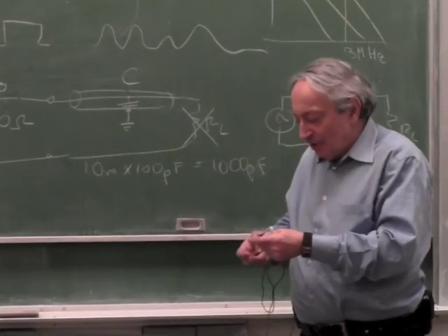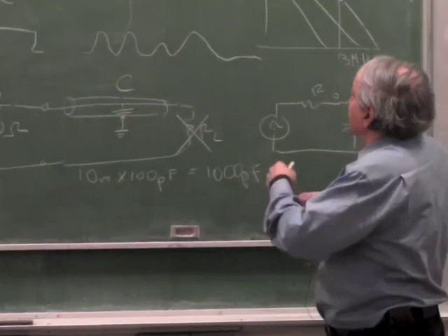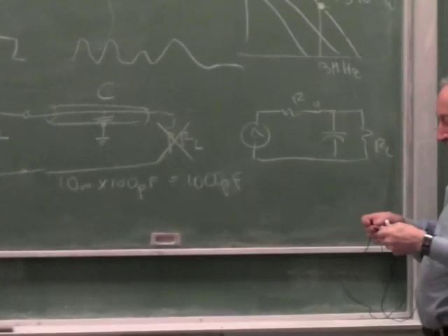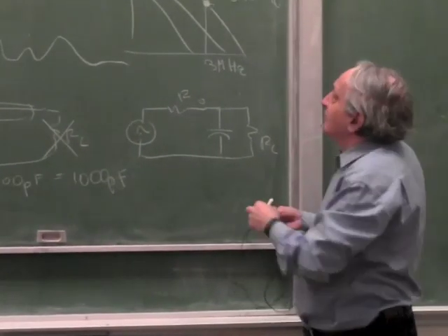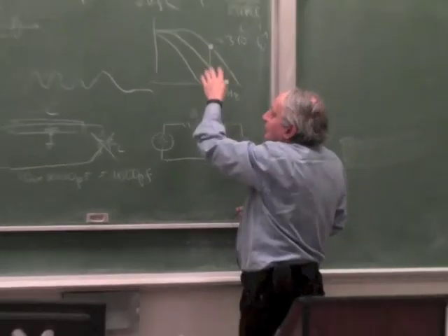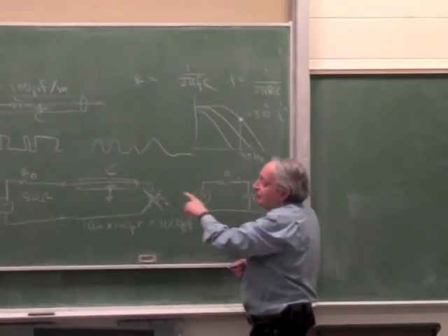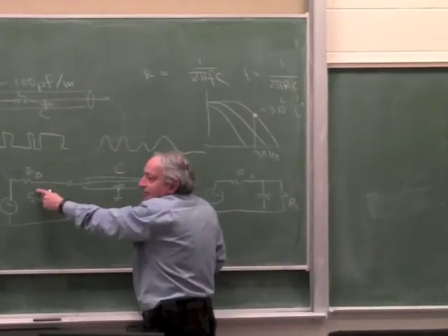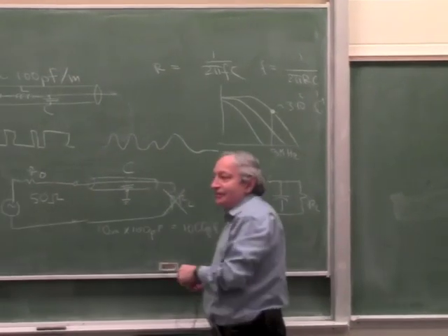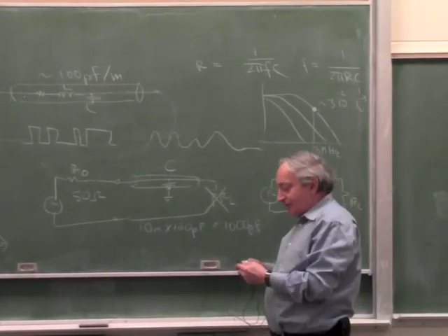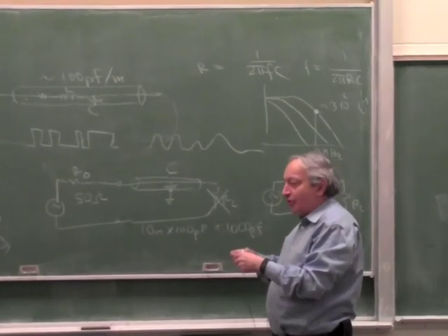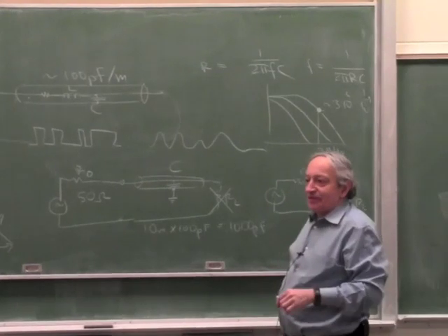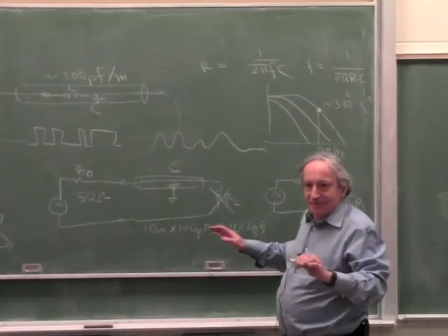So whenever you put a piece of cable, you calculate this number. If this number is high enough compared to your frequencies, you don't need a coax. But if this number starts getting close to a few harmonics above your frequency of interest, you have to switch to that. You have to use coax. Or you have other choices, lower this resistor. If this resistor is very low, it can drive the capacitance much better. So there's more than one choice, but basically you have to be worried that the waveforms will be distorted. Okay? Clear? Good.